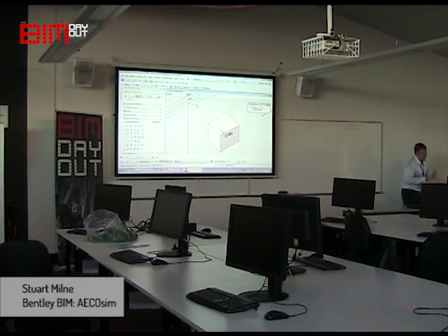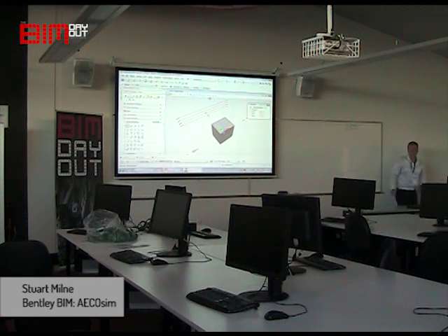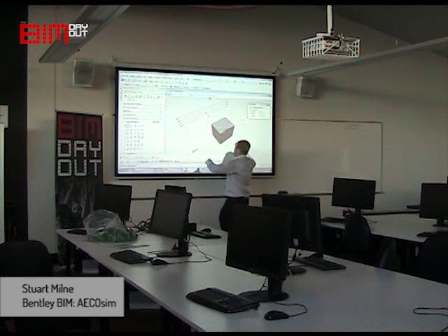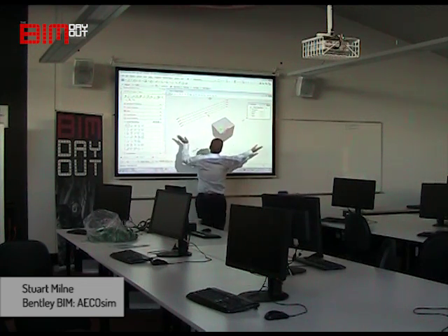Okay. Now, this little toolbox over here is all about giving the view some perspective. At the moment, we're on what's called a parallel view. We have no perspective going on there. So what you can do is hold down this button with your left mouse key and some other tools appear. One of them, the second one down, is extra wide camera. Click on that, and you can see now that we've got some perspective. And you can tell because the edges that go up the z-axis are no longer parallel to the screen. They're on an angle.